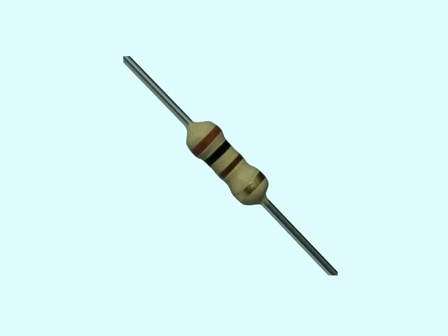Now, resistors are usually a little bit too small to actually print how many ohms are on there. So if you notice in this picture, there are different color bands that go around this resistor. We'll talk about that a little bit more later, but the different color bands tell you the value. There's a decoder ring, so to speak, where you can look up the colors and figure out what the value of this resistor is just from the color bands. So usually you will not see 10 ohms, 20 ohms, 30 ohms printed on the resistor, but these colored bands basically tell you what the value of the resistor is without actually having to print it on there.